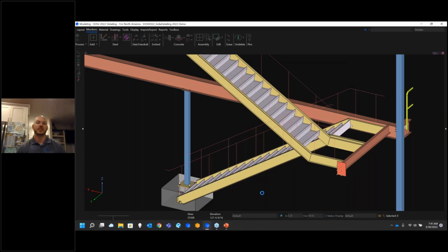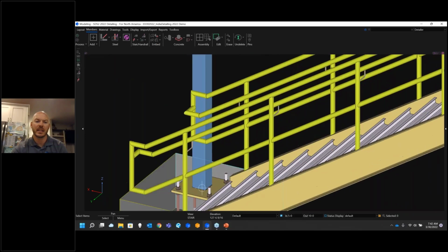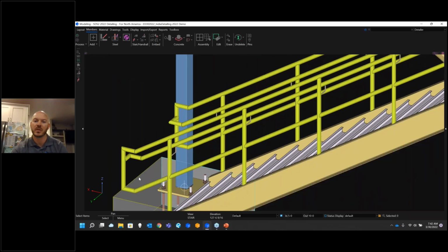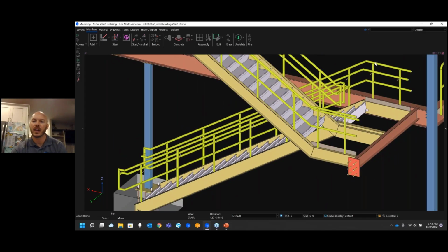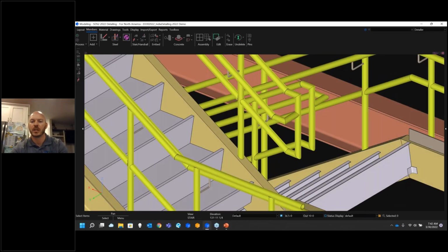Okay, so I'm just putting in a basic 2-pipe rail, but this could be anything. We can use tube material, we can put pickets in there, whether they be round pickets, square pickets, tube posts, angle posts, a number of different options within the handrail. And you can see I added these, everything I have set up is just to do a nice miter on everything. We can see that interior, how that works out as well, the way that I input that.